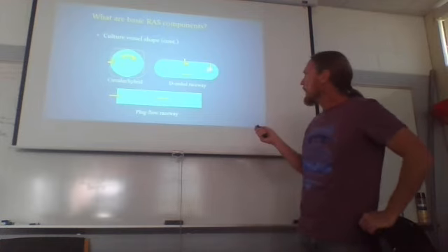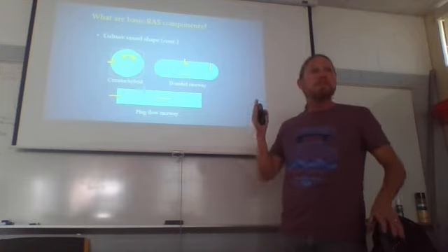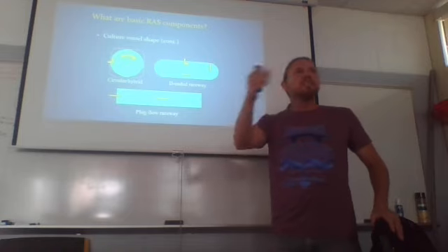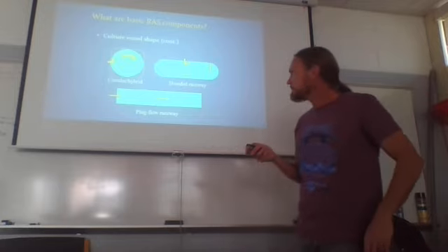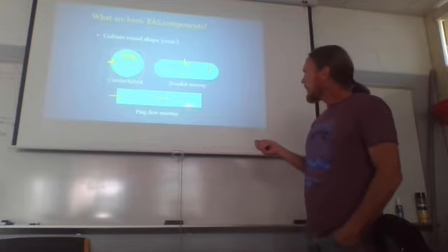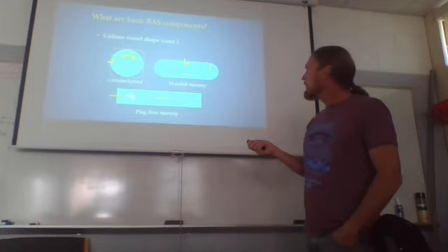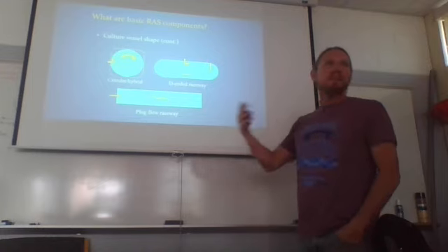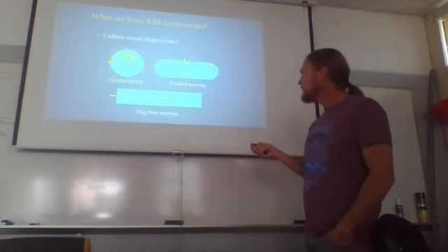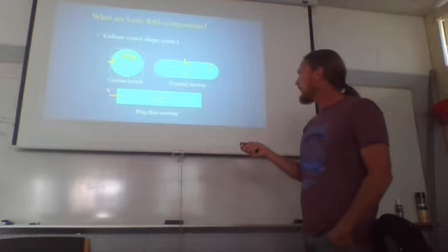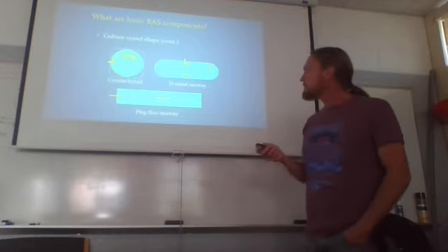This D-ended raceway, you have a long oval tank with a divider in the center and a directed flow creating motion like this. This is nice for fish, like I was describing, that might tend to stay right on the edge and rub their face against the side of a circular tank, but that need to keep moving. A plug flow raceway. This is good. Now, a tank like this is going to require a lot of water input too to keep this motion going, to make it really amount to anything. But you've got an input at one end, outflow at the other end, and flow going right across.